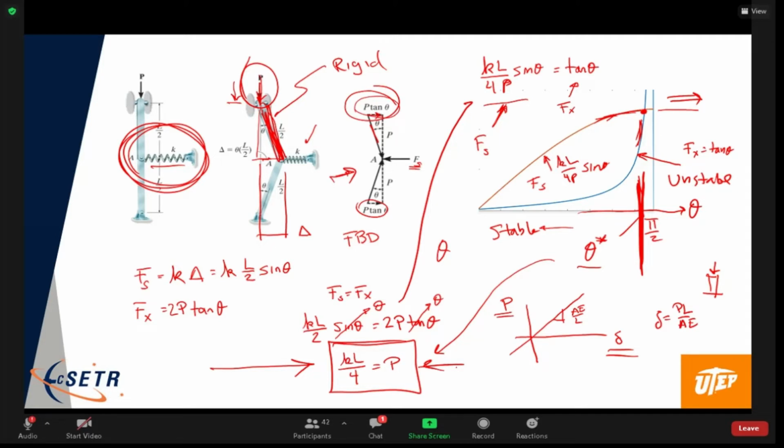And if you look at the buckling on my camera, as I increase the force, nothing happens, because the spring is able to push that node A back in line. Once I hit the force equal to this critical value, it bifurcates, and it always wants to do it out of the screen, and it bends significantly out of the plane. That is the critical buckling load.